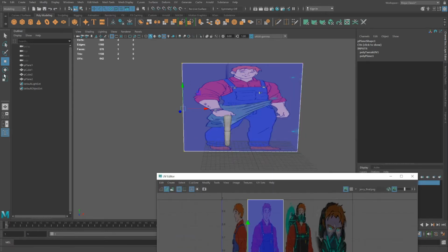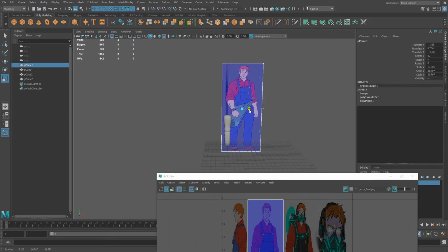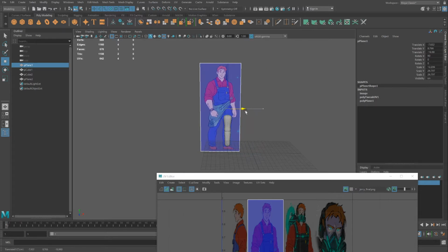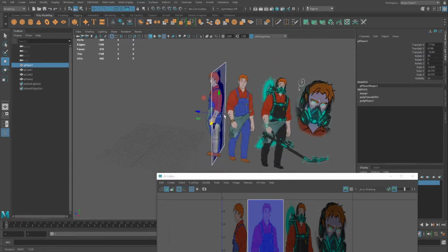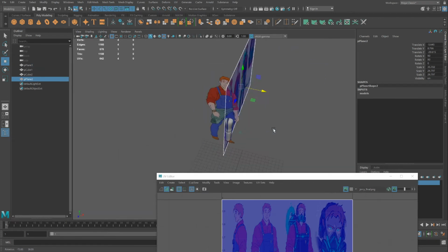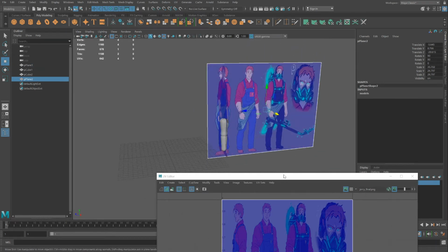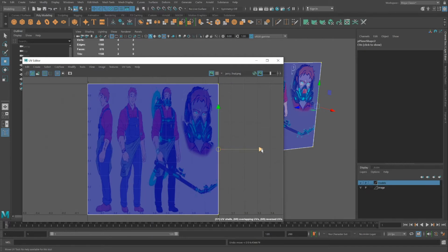I could have done this first, and maybe I should have done this first. I was just freeform thinking out how I could create this character. And my conclusion will be, yeah, doing one of these X-plane things will work out. If I need to hide the rest of this, I'm on that secondary image plane. Right-click, vertex, selecting those vertices, going to the UV editor and moving over the UVs.